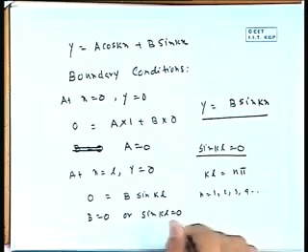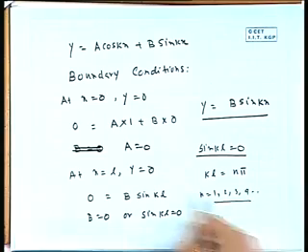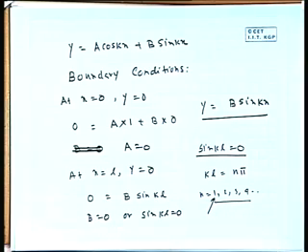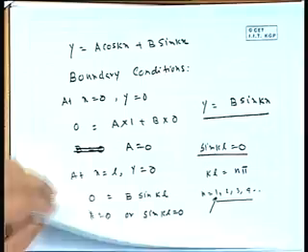So it is entirely 0, right? But here we are interested, n should be at least 1, 2, 3, 4, some value. Now n may be 1, 2, 3, 4, anything. It may be 0 also. 0 definitely we are not interested in, because 0 again will give that free buckling case. But normally 1 is a very sensitive value. Now we got KL equal to n pi.